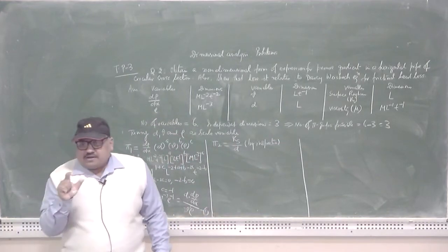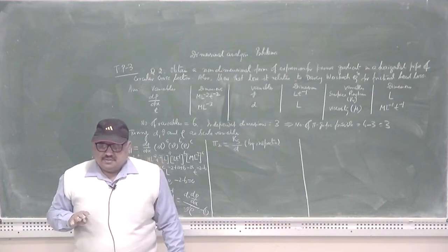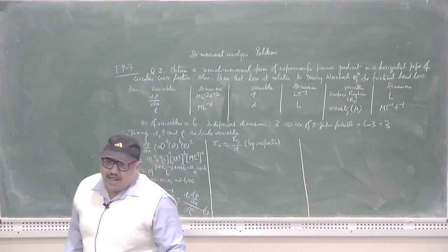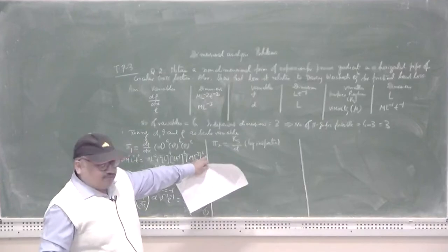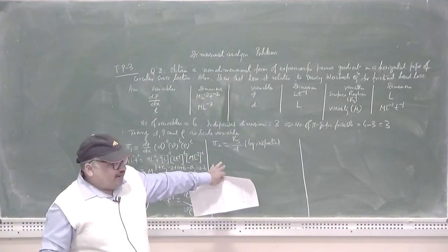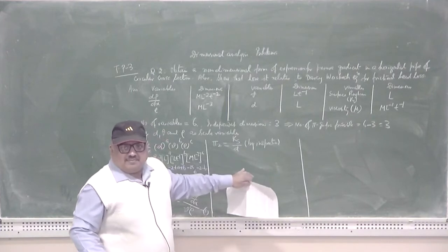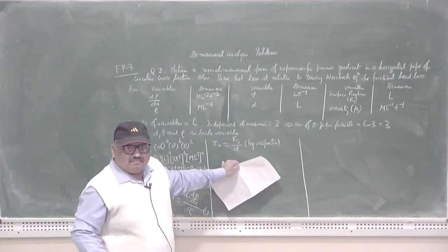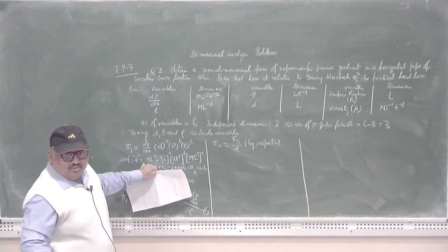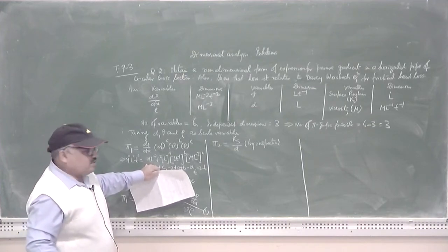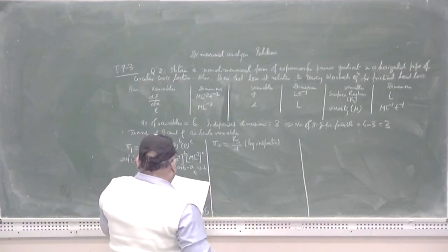So, your work has been reduced a little bit. However, if you apply the Buckingham pi theorem, in that case as well you will obtain this group. You can see at your respective home that this is the second pi group that will be obtained, utilizing the principle that I have discussed in order to evaluate pi 1. So, pi 2 is equal to Ks upon d.